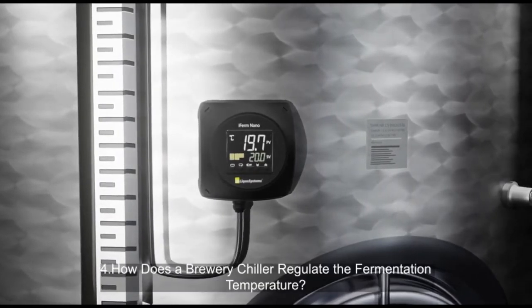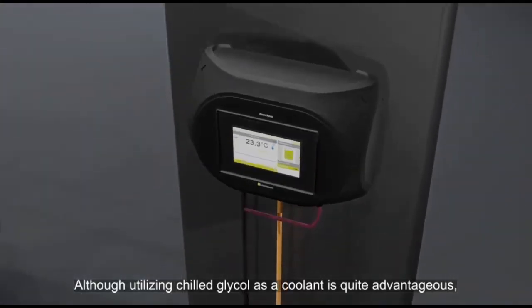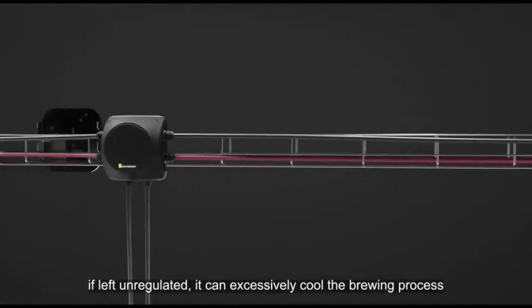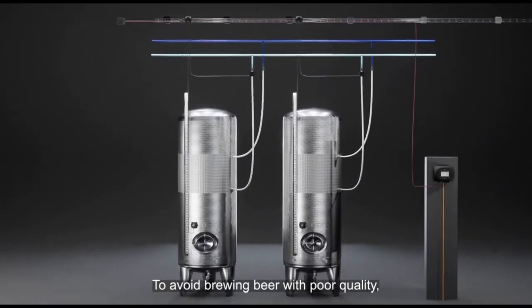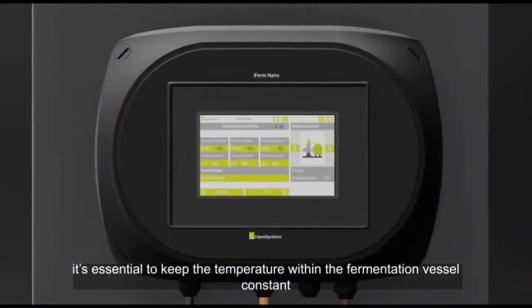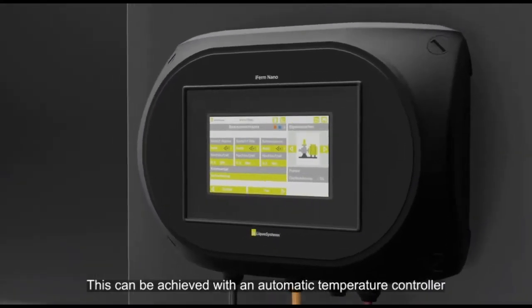How does a brewery chiller regulate the fermentation temperature? Although utilizing chilled glycol as a coolant is quite advantageous, if left unregulated, it can excessively cool the brewing process. To avoid brewing beer with poor quality, it's essential to keep the temperature within the fermentation vessel constant. This can be achieved with an automatic temperature controller.